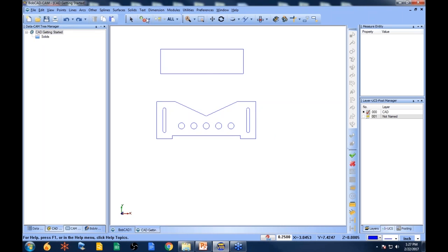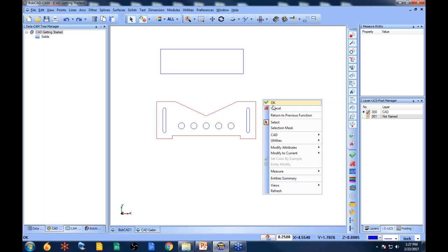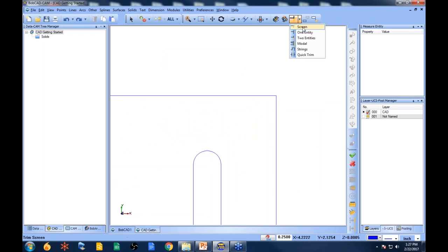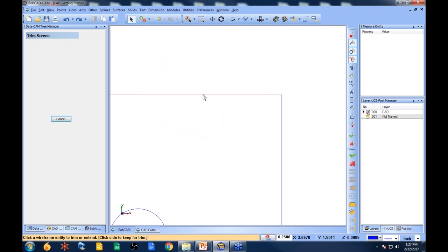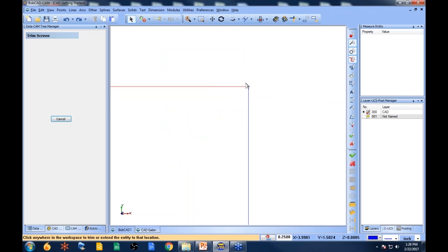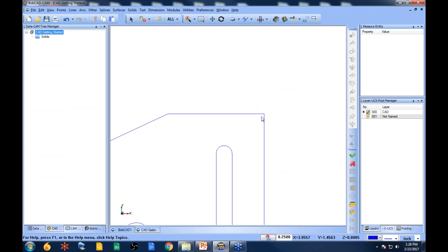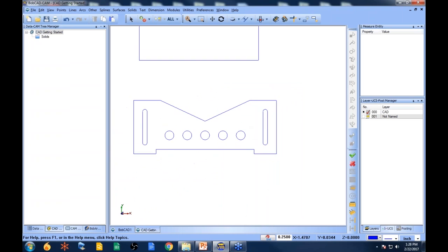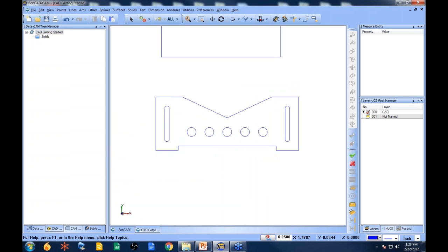Really, all you do is you go to selection mode, you shift click, and wherever it stops, if it stops right here, there's a lot of different reasons why this could be, but usually there are little breaks like this. See this little break here? That's generally what it is. Sometimes it's arcs with smaller segments like non-tangent segments, or when they didn't trim the geometry together.